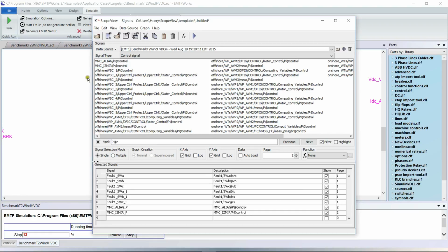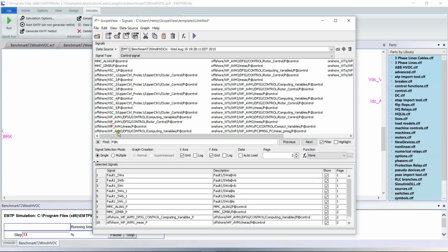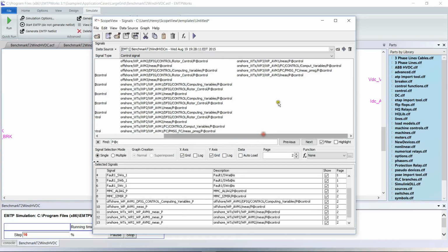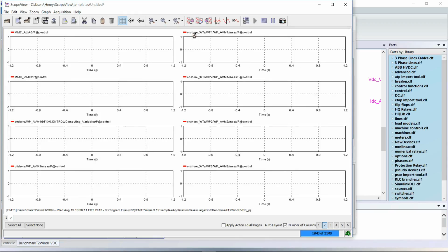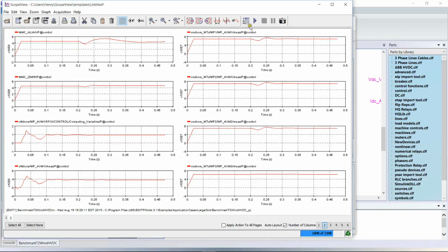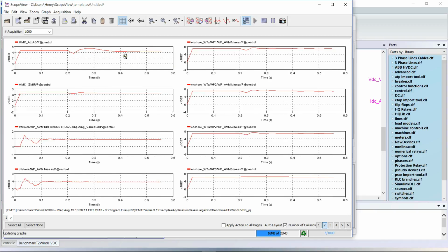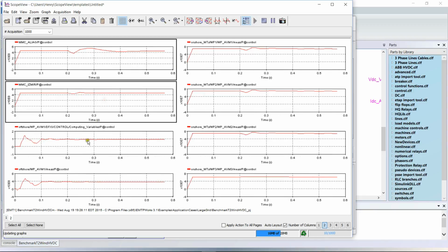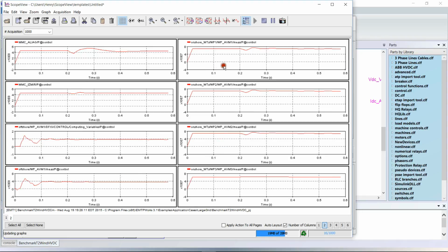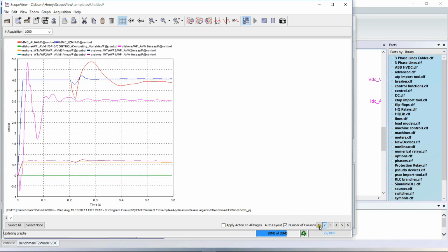MMC. Okay, and we can put the power generated by some of the wind turbines and see if everything converges after the fault, during the fault first, and once the fault is clear. Okay, so we can display all that during the simulation. Actually, we can make the plot refresh during the simulation. We just have to put several acquisitions here, so that it evolves during the simulation. It's dynamic. I mean, it's a nice feature. It's not new, but it's still pretty nice.